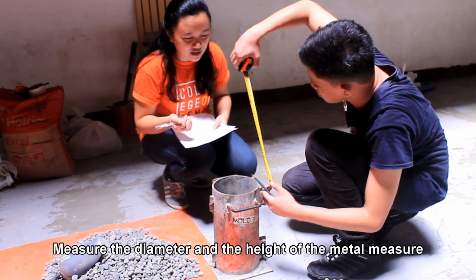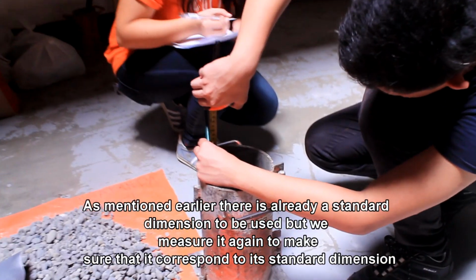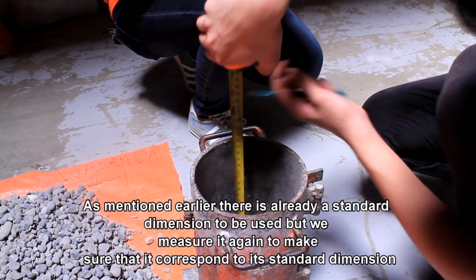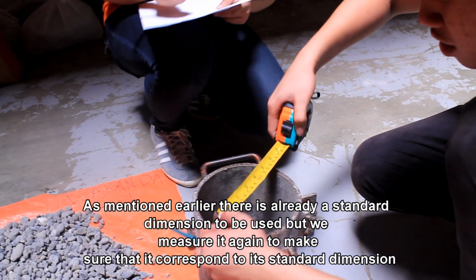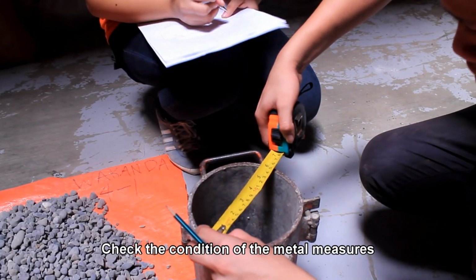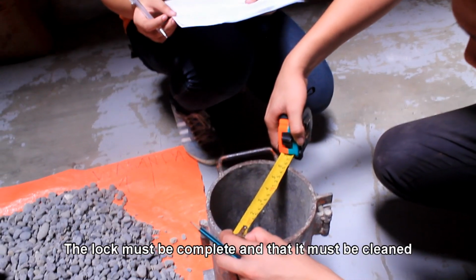Measure the diameter and the height of the metal measure. As mentioned earlier, there is already a standard dimension to be used, but we measure it again to make sure that it corresponds to its standard dimension. Check the condition of the metal measures. The lock must be complete and it must be clean.